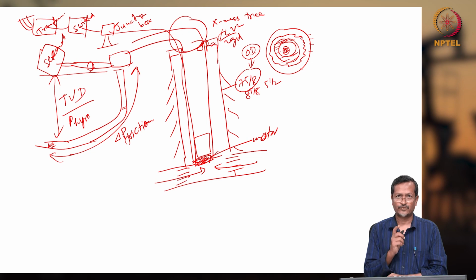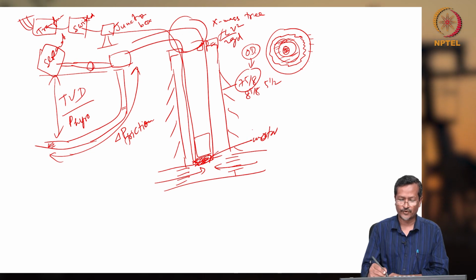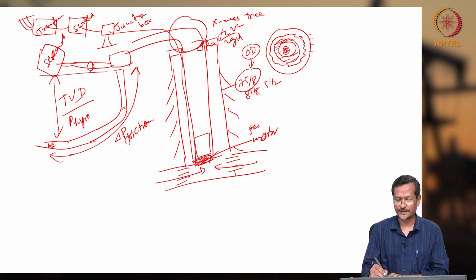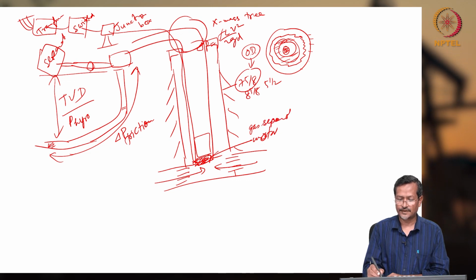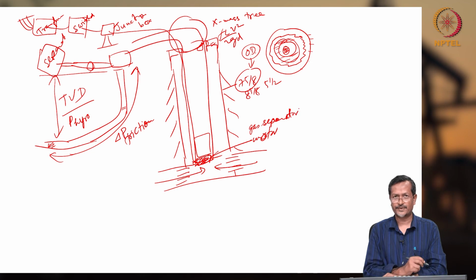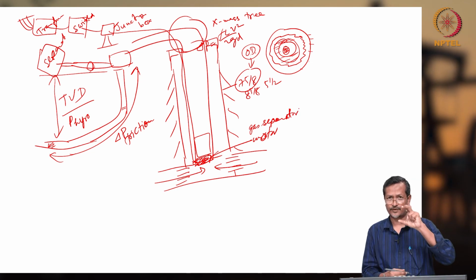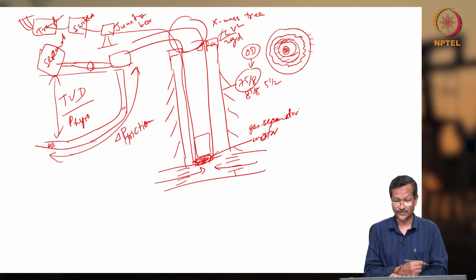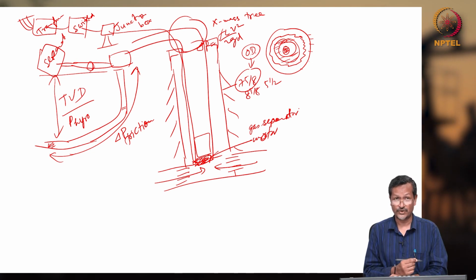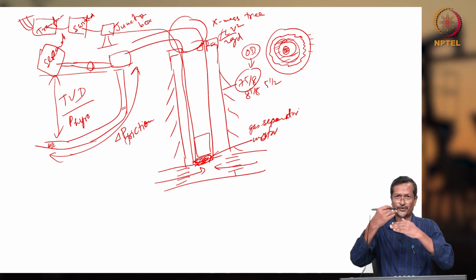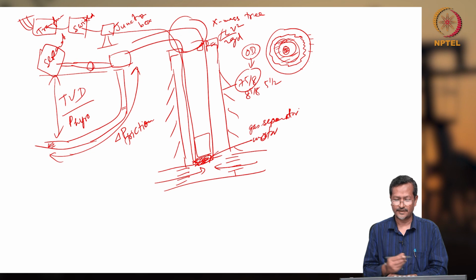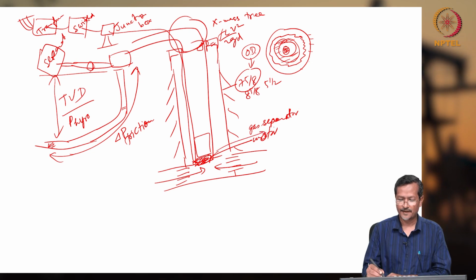Okay, so you must have one gas separator here. Before the motor, after the pump, there will be a gas separator. What will be the location of the gas separator? Just before the pump. It is called the intake section. At the intake section, there will be one gas separator. So the gas separator will contain your inducer also, so that will give some NPSH. And in between the gas separator and the motor, there will be another piece of equipment. Can you remember? That is called the protector.